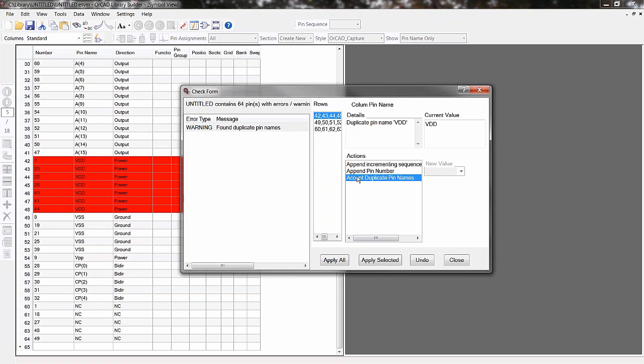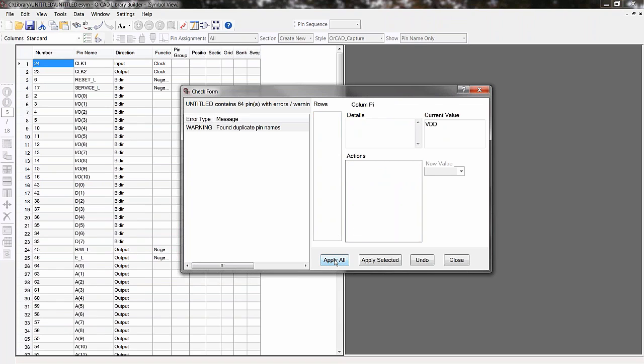It's just that you'll get a warning message in OrCAD itself when you go to save a new symbol, let's say, that you were creating where you created multiple VDD pins. But it is acceptable because the netlister will handle it. What the netlister actually does is increment it by itself. It'll put an _1, _2, but it's in the netlist versus being on your graphical symbol. So I'm going to say accept duplicate pins.